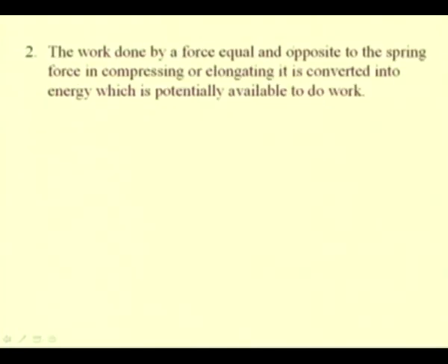The same way we can define it for the spring force: the work done by the force equal and opposite to the spring force in compressing or elongating the spring is converted into energy which is potentially available to do work. So, again we write this potential energy Ve as the total work done by this force F in displacing. So, the integral of F dx is the work done from the undeformed position, which corresponds to 0, to any particular position x, which is equal to half k x square.